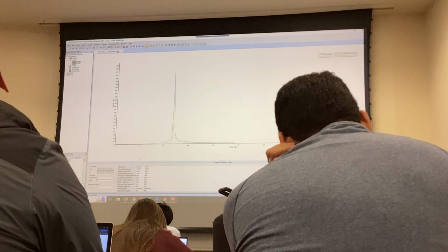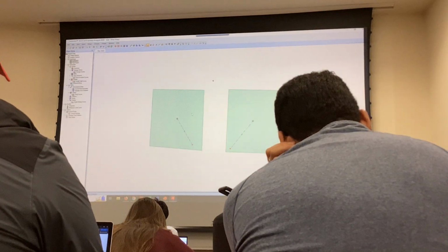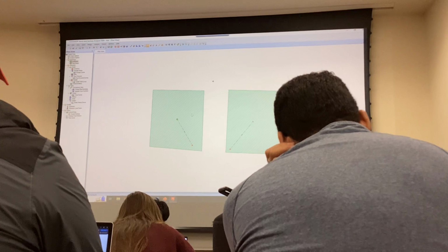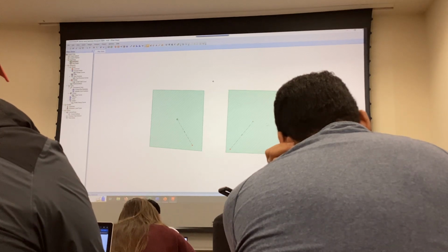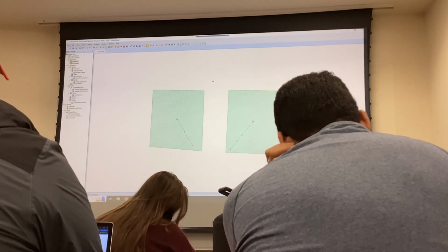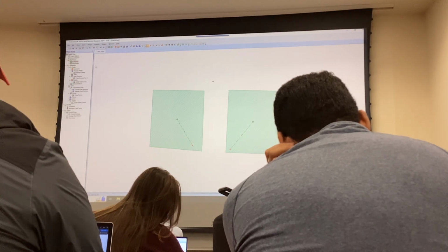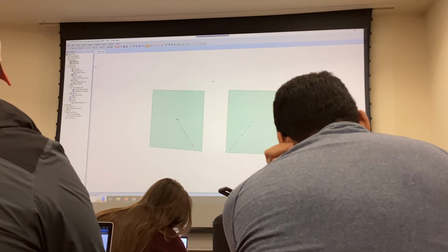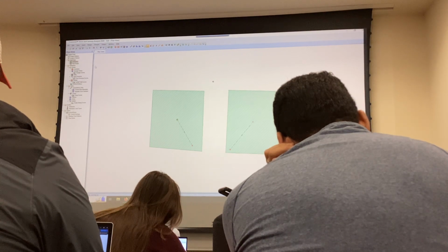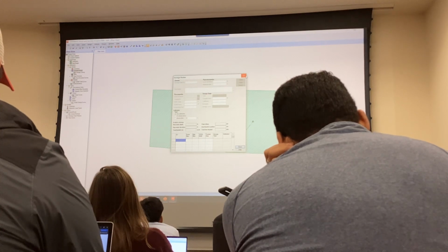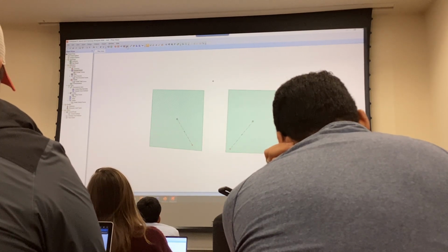So the way to do that, I'm just going to go to this first. Okay. The way to do that is, so this is pre, this is post, right? So the way to do that is you add something called a storage node. The detention basin is basically a storage node, right? So you add a storage node by clicking on this one button, or you can click on this button here.